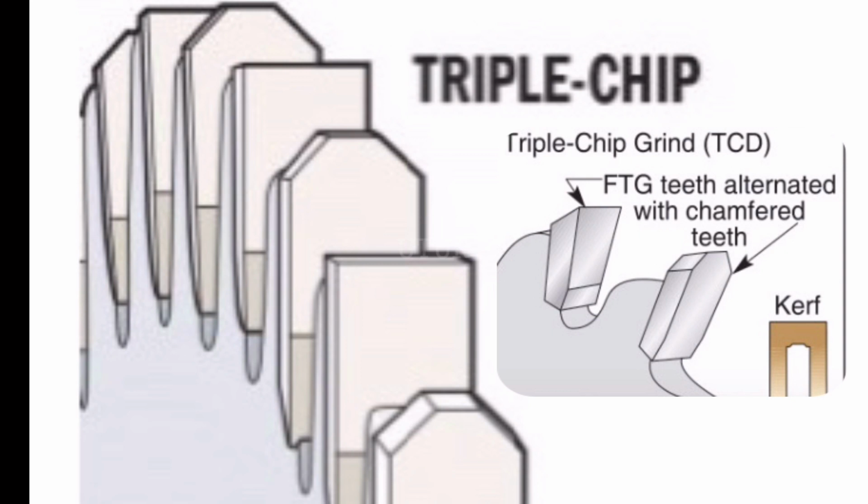They don't have scoring bevels as in the case of the ATB, so the TCG is very durable and is used on glue line rip blades, blades for melamine board, laminates and other manufactured materials, where tooth durability is most important. The TCG geometry is particularly suited or designated for particle board products and abrasive materials, like your melamine and MDF.